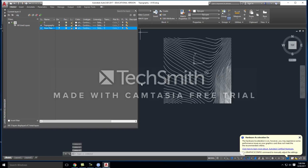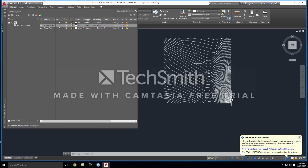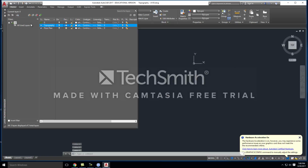All right. If you find the topography a little bit distracting, that's okay. You can go ahead and just turn it off for now, or whatever you need to do is totally fine by me. I'm going to turn this off for demonstration purposes. Let's go ahead and freeze it, and that will turn that off right there. And I'm going to make my active layer my floor plan by double clicking on floor plan.